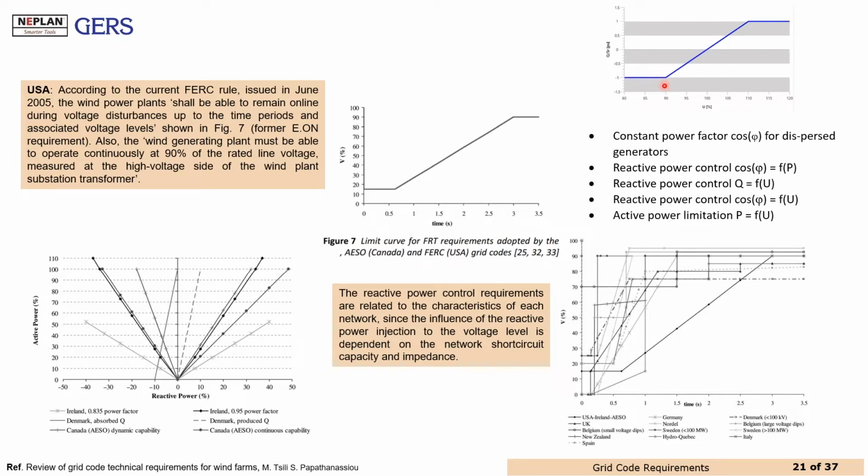And these kinds of technologies are mainly used to support reactive power injection. If we are speaking about variable renewable resources generating active and reactive power, we have here the prioritization between the active power and the reactive power. And we have here also the specification of the active power limitations, where the active power could be a function of the voltage.